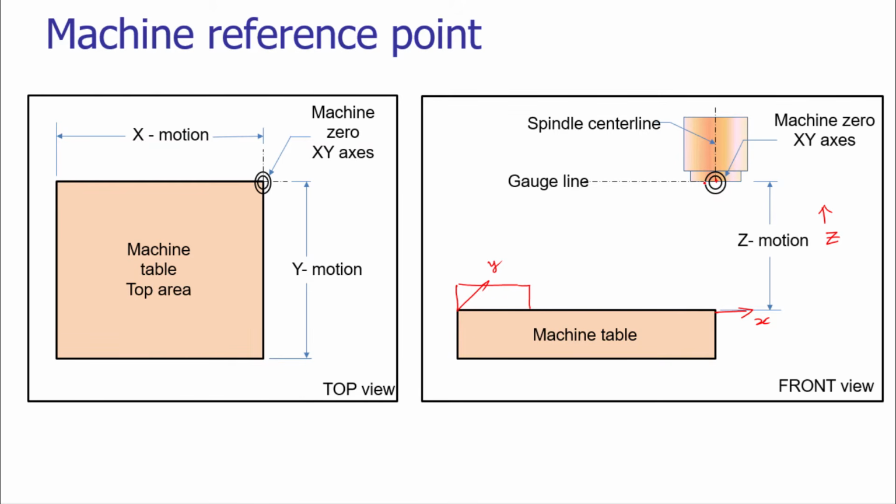So here we are mounting the tool as well. The cutting tool will be mounted. This cutting tool is mounted in this way. We are communicating the length of the tool to the MCU as well. We need to provide the information about the cutting tool, its diameter and length.